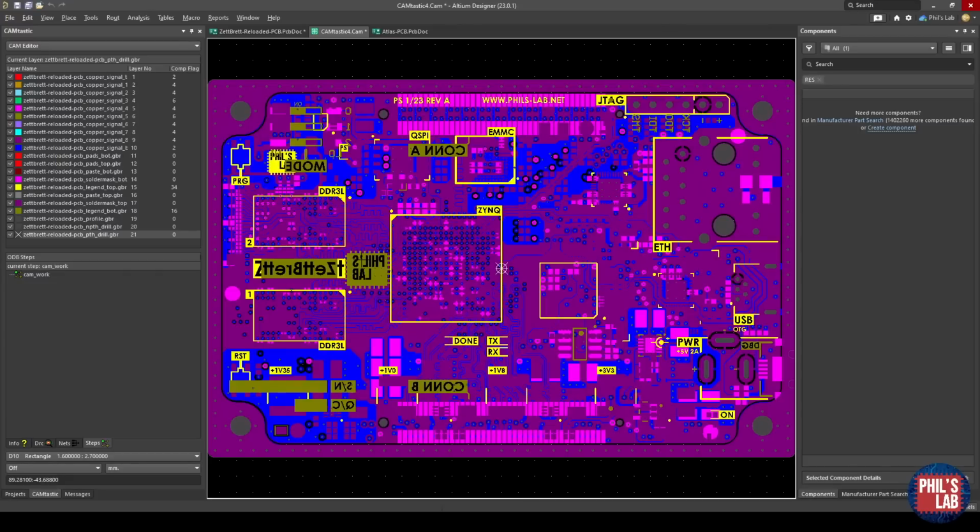Click Apply, and Altium Designer or your ECAD tool of choice will start generating these Gerber files for you, or plotting them. Usually what is then opened is known as a CAM viewer. This is the tool which allows you to view Gerber files. I highly encourage you to check your Gerber files thoroughly. A lot of the times I might check little inconsistencies or maybe even little mistakes just by looking at my Gerber files. It gives you a slightly different view of the layers and shows you, for example, what copper will be actually left on the board or the layers.